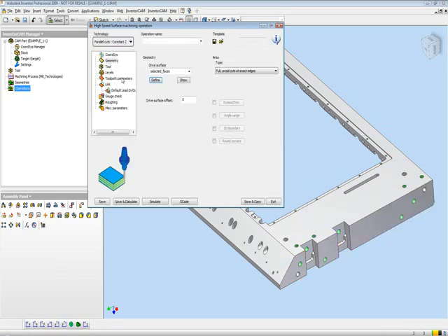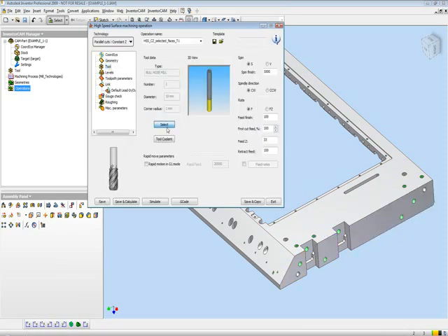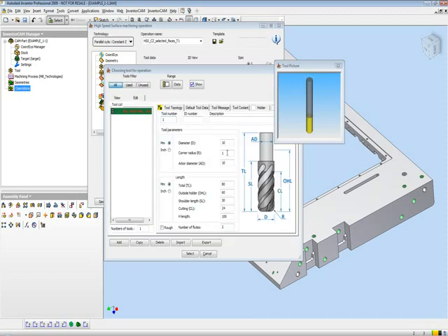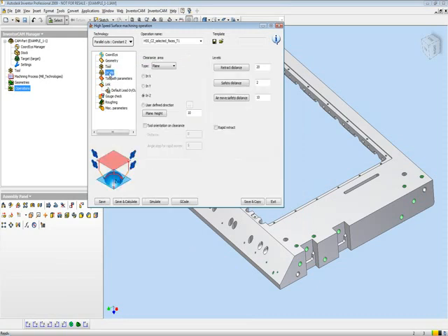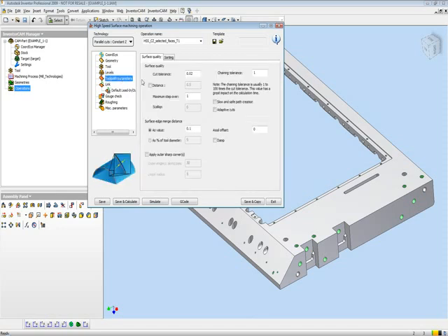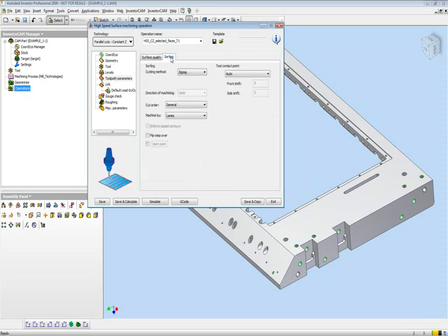Now the next thing I must do is choose my tool, and in the tool area I'll be using a 10mm bullnose tool with a 1mm radius at the corner itself. My levels, I'll leave exactly the way they are, and now I'll go into my Toolpath Parameters. In my Toolpath Parameters, I have control of my maximum step over, and in this particular case I'll make it every 2mm. In addition, I have my sorting area where I can work zigzag, one way, or spiral, and I'll use the option of zigzag going back and forth.